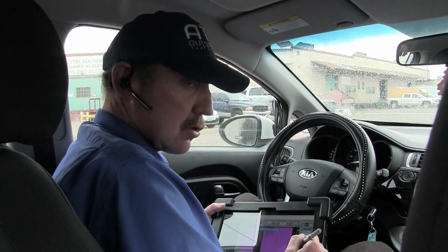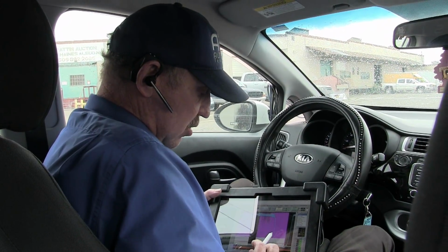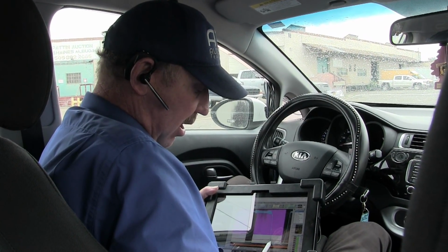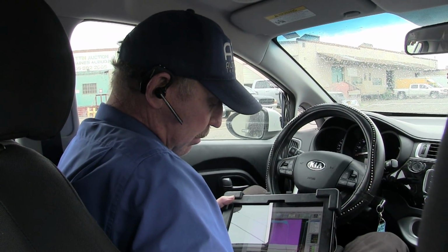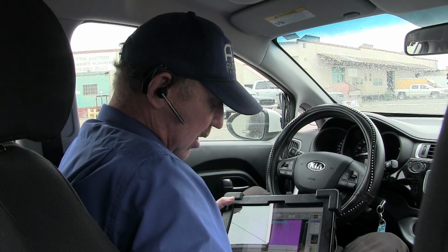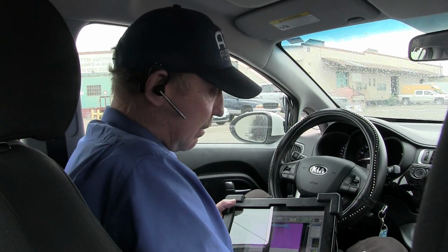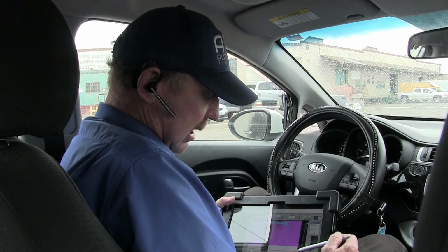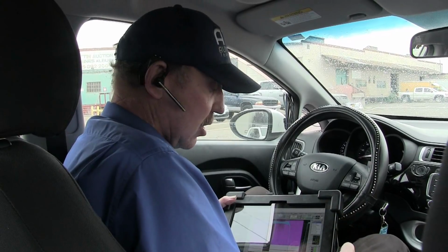This car, guys, has a restriction somewhere in the line. There's some restriction, some way this is restricted. So when I get it under load and I need more fuel, the fuel is just dropping off because it can't keep up with the volume. It can't keep up with the volumes because it's restricted. Now I know it's restricted because the RPM of the pump did not change. And to go from 60 pounds to 0, that pump is going to take off. It's going to be turning 8,000 to 9,000 RPM. So right here, it did not do that. So if it didn't do that, then the pump is still seeing the pressure against it.